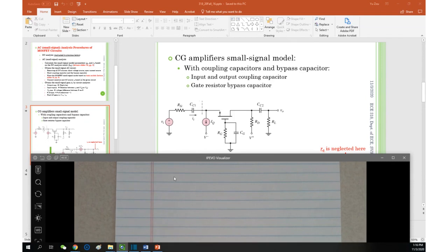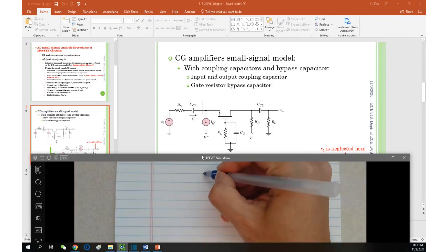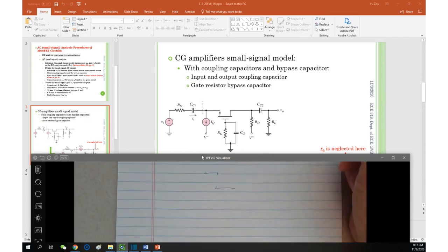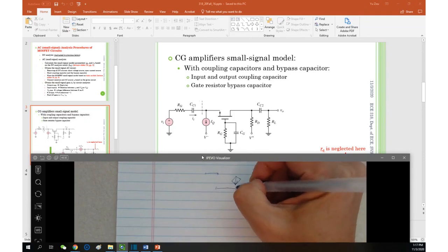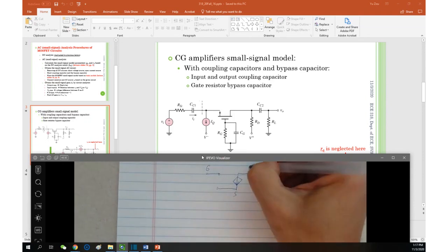After this, we place the small signal model of the transistor right in the middle of the paper. Is this an N channel or P channel? It's N channel, so I start to plot. You don't need to memorize this because it is on your cheat sheet. You just copy and paste. I'm serious on this. Don't try to memorize it, it's wasting time. Gate, source, and drain.